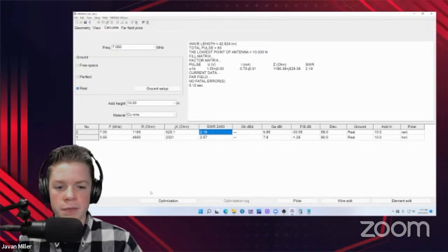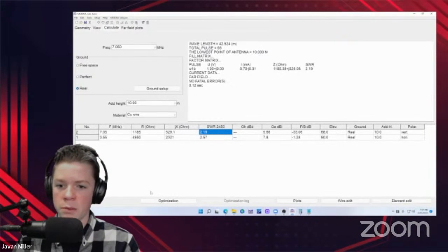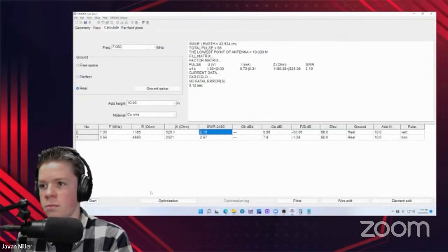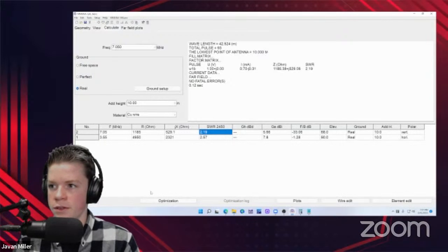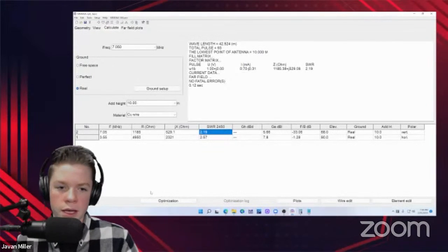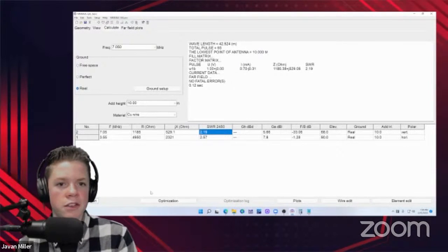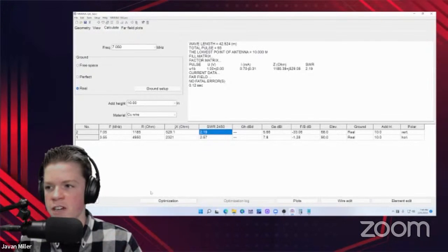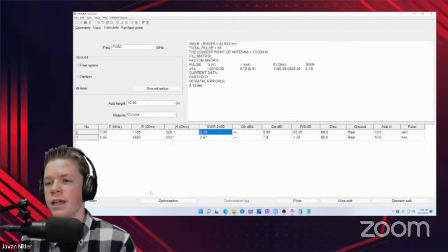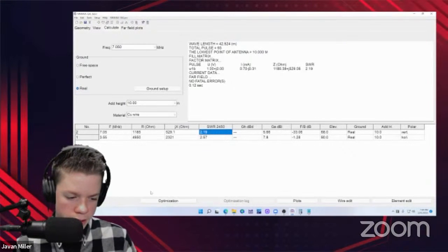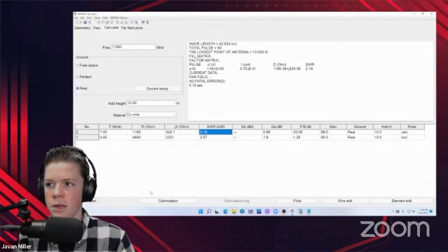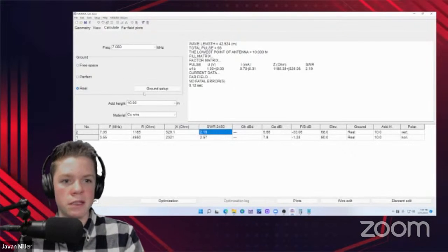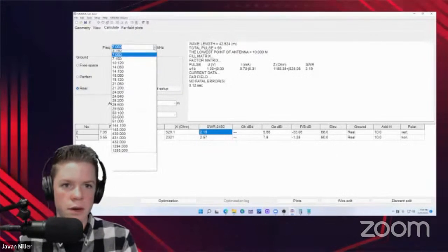The resonant point on 40 meters is going to be half of that, so it's going to be around 7.08 megahertz or something, and on 80 it's going to be half of that. And just because of some ground effects and different interactions, it actually might be a little bit lower than that. So you're not going to be able to make the antenna resonant up on high 80 meters. It's going to have to be resonant lower. Let me lower this a bit here, so we can see what's going on.